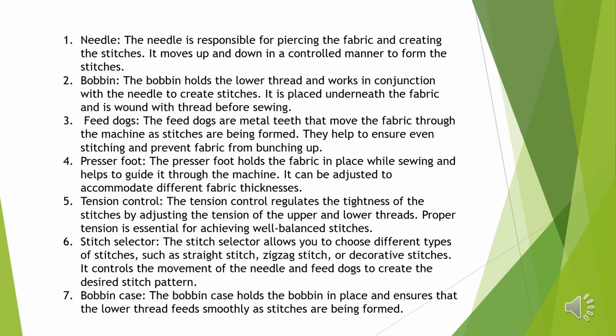Next, we have the presser foot. The presser foot holds the fabric in place while sewing and helps to guide it through the machine. It can be adjusted to accommodate different fabric thickness. Next, we have the tension control. The tension control regulates the tightness of the stitches by adjusting the tension of the upper and lower thread. Proper tension is essential for achieving well-balanced stitches.